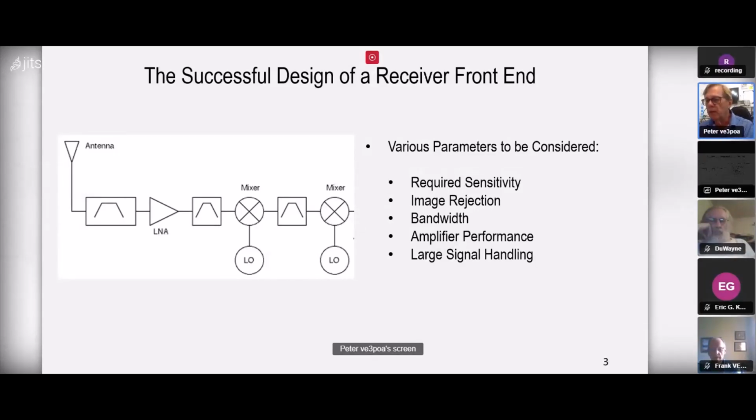The PCB layout. Pay attention to the physical layout of the components to minimize parasitic effects, signal degradation, and crosstalk. Follow best practices for RF layout, such as maintaining proper trace widths, separation, and grounding techniques. And that we did do with the Phoenix. The 12 volt a little bit larger, RF a little bit smaller, just depends, and try to keep things separate as possible.